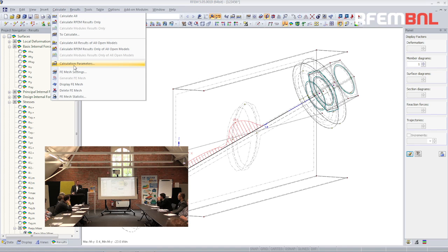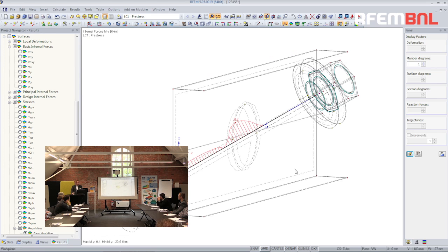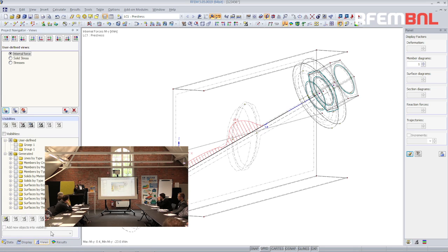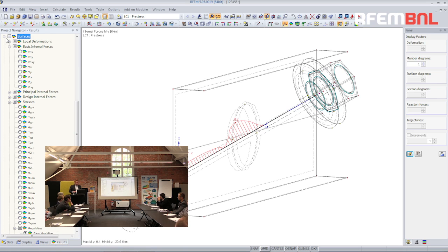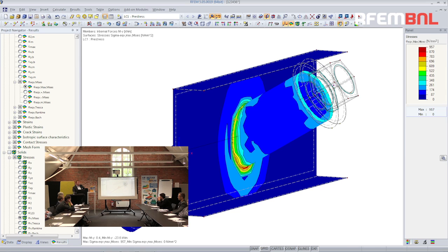If the local value gives negative contact stress, then you have to reduce the stiffness. Okay, like that. Do it again. Now it will run a nonlinear calculation, and when you open a model like this from a colleague, you have no clue what is inside. You can always check. Did he use something nonlinear?